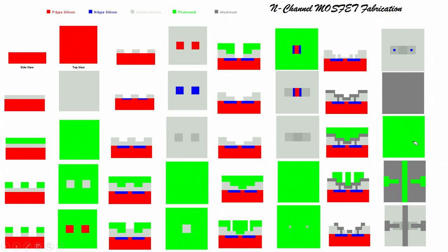what we have done here, starting with here. Okay. Concentrate, p type silicon we have taken, then we have grown silicon dioxide. On this silicon dioxide we have spin coated photoresist. After that we have done lithography. Lithography here means photolithography.